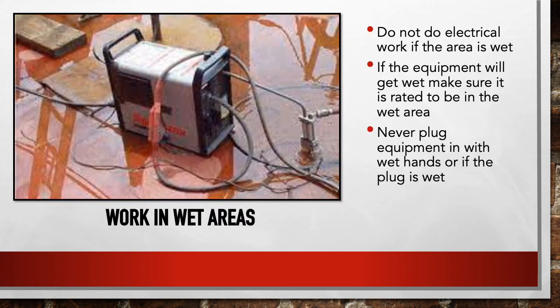All right, work in wet areas. Obviously, using electrical tools and equipment while standing in water, not a great idea. Some pretty easy ways: you can use elevated platforms, non-conductive work surfaces such as rubber mats, not pallets, obviously, because wood is conductive, especially when wet. Stone, etc., to prevent you from coming into contact with a potential circuit. And obviously, lifting the tools and cords out of the water is also an important component of this. So don't work around or with equipment if you're wet or anything's wet. You want to make sure everything's dry, as it is the intended atmosphere to work around electrical equipment.